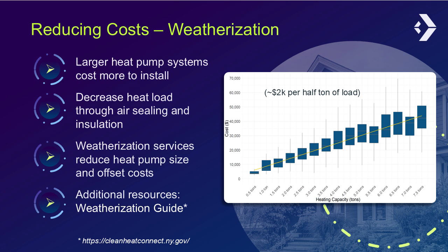First is to bring down the heat load by air sealing and adding insulation. Basic weatherization services where the savings from needing a smaller heat pump system surpasses the cost for weatherization. This link to a fact sheet from cleanheatconnect.ny.gov goes into this trade-off further.